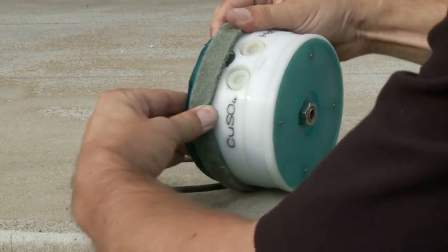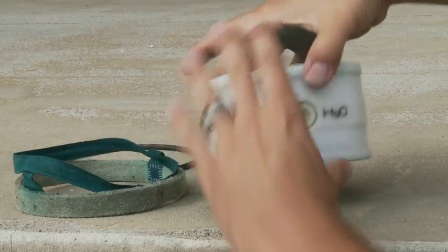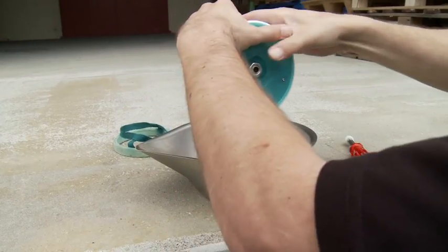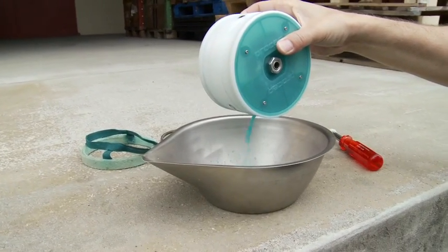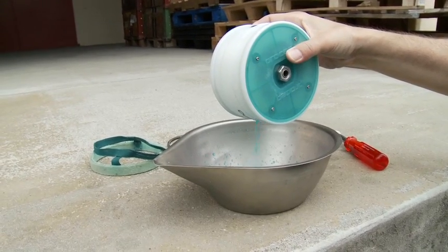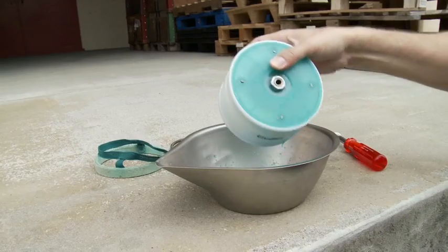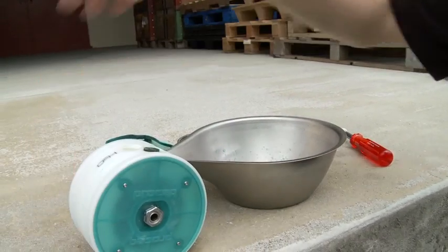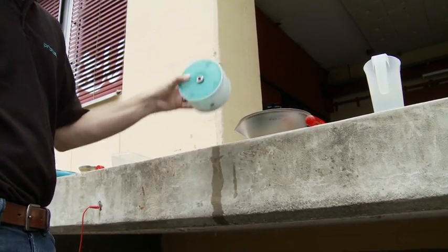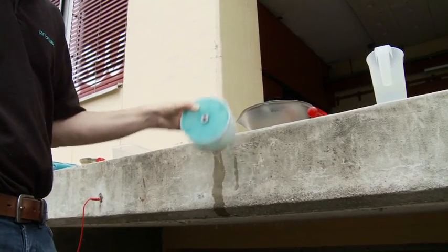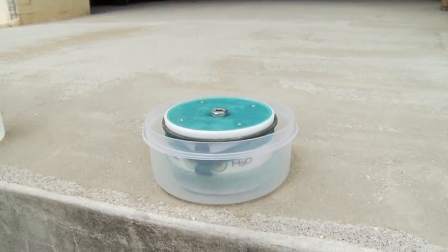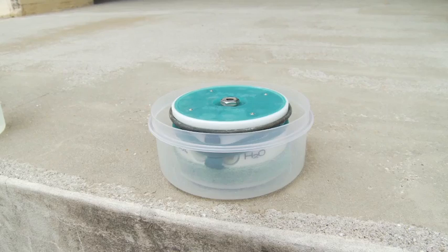To maintain the wheel electrode, remove the felt hoops and wash them in lukewarm water. Remove the plastic filling screw and pour the copper sulfate solution into a container for reuse. Flush out the compartment several times with water. Then dissolve 1 part of citric acid in 10 parts of hot water and half fill the wheel. Replace the filling screw. Leave this for 6 hours, shaking occasionally. Then pour out the citric acid solution and flush out several times with water. When not in use, store the wheel electrode with the wooden plug facing upwards.